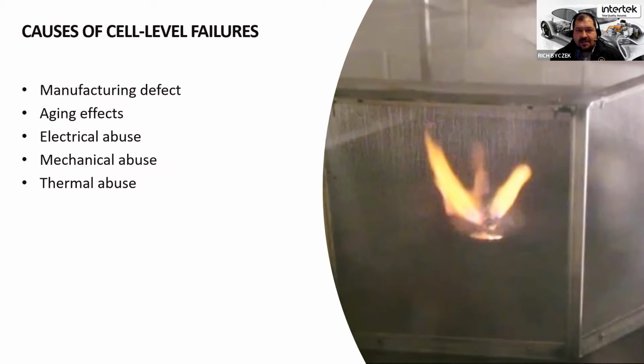Thermal abuse simply is just overheating the battery, where you actually drive the temperature of the battery such that some of those other side reactions, other chemical reactions that are unintended within the battery, can be triggered just by the temperature alone. And that also would then cascade within the cell, so that even if you took away that external heat source, the battery reaction has already started. It's creating its own heat, and therefore it can propagate or at least go into a full thermal runaway.